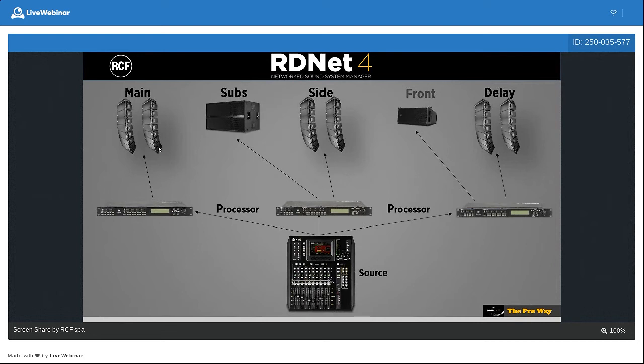we need to go to the cluster with more than one audio cable. For example, to equalize the speakers differently according to the HF compensation, for example, or in particular talking about subwoofers, different configurations of subwoofers. Let's suppose to do a sub-arc, okay, of 10 subwoofers.